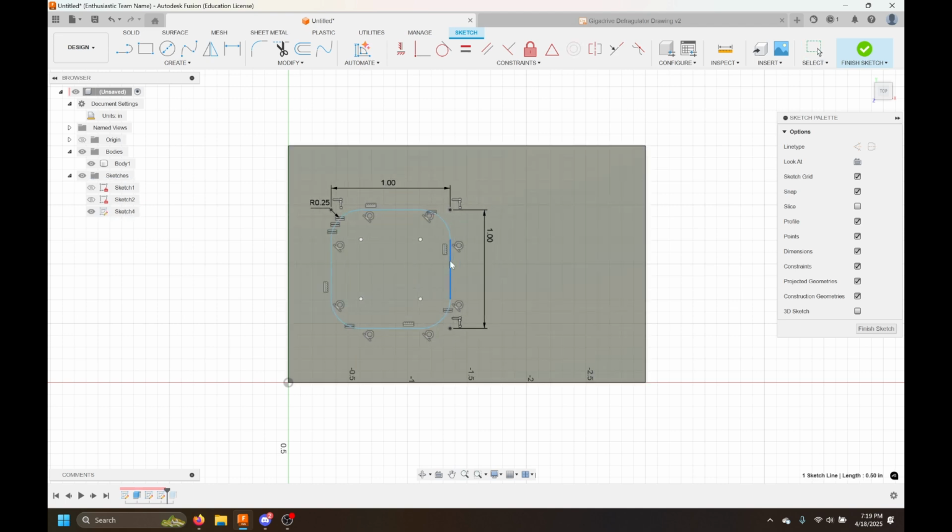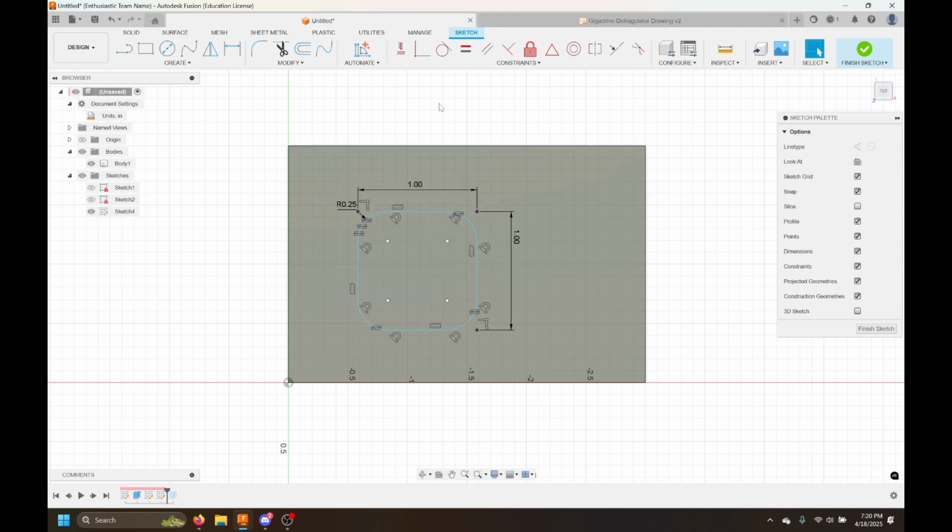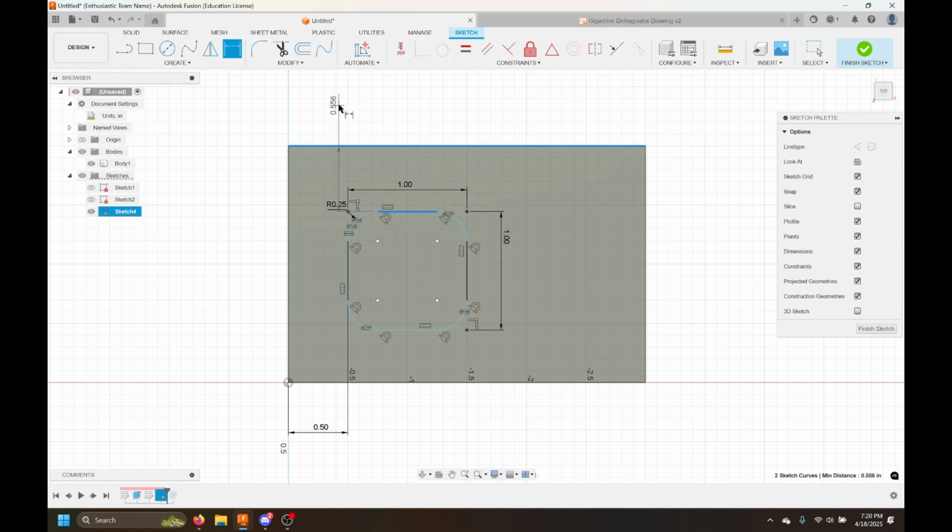From here we've got this nice shape, but it's not constrained. You could put this anywhere in here. Even if you eyeball it really close, it's probably not correct. So I'm going to set its dimensions in the space. We're going to go from the left side, this line, to this line. This is another use of the dimension tool. And put this anywhere. I'll just drop down outside our part at 0.5 inches. And then I'll do the same to the top.